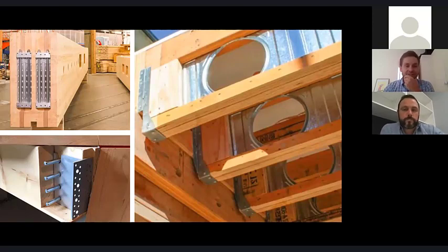Yeah, so essentially just a slide of some connection examples, not all really related to a hotel necessarily. Obviously, that's a Lend-Lease International House up on the top left. I guess the main point here is, firstly, manufacturers of these brackets and connections can certainly assist you with the design. Your vertical and sort of lateral loading is pretty straightforward from an engineering perspective. I guess with connections, the biggest challenge generally comes around robustness and understanding how you're approaching robustness and whether or not these systems can accommodate the design requirements of that.